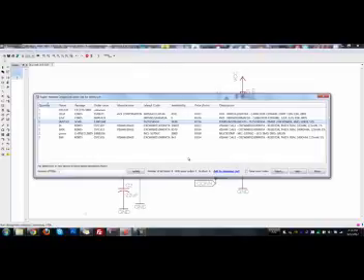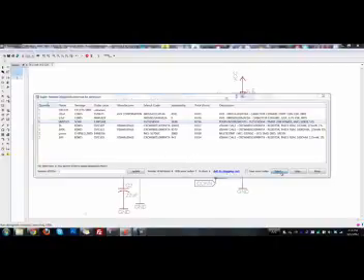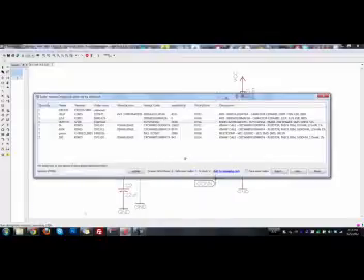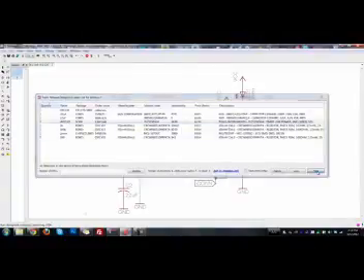If you've done circuit board layout before, you know that's usually really annoying to pick out all the parts. We just did that in just a few minutes, which was really great. So from here, you can even go on to ordering the PCBs and stuff. We'll talk about that in the third tutorial. But for now, we can add these to our shopping cart, or we can export it as a bill of materials that we can use later to find and order all of our parts. And we have the manufacturer part numbers and all that information, which is great.